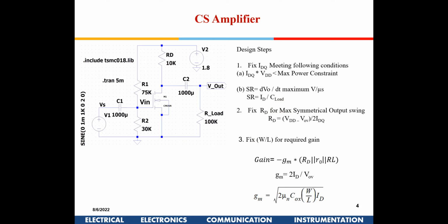For each requirement, generally if this is the 180 nanometer technology and 1.8 volt is available, and your signal levels are within say 0.6, 0.8 volt, then we go like this. But if there is a requirement of higher voltage, then you might want to use a different technology device altogether, like power MOSFETs or something which operates at higher voltage.